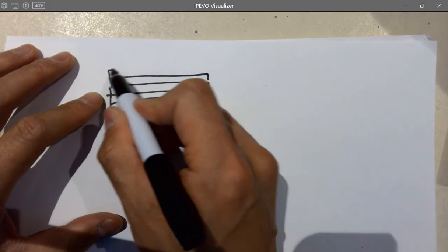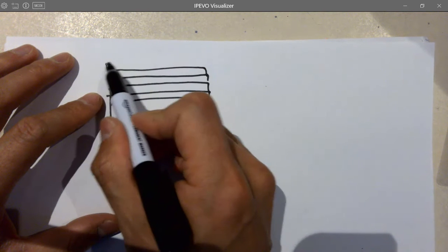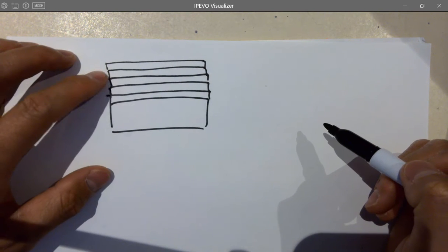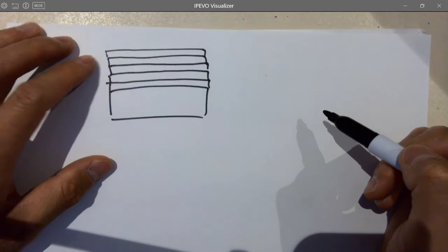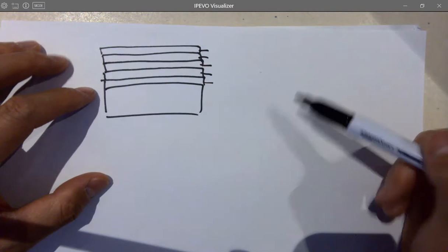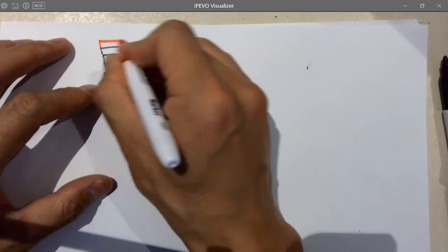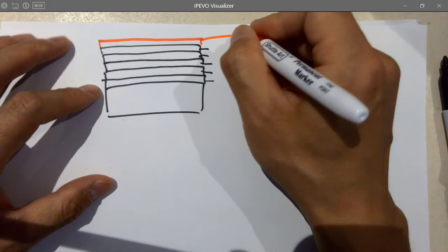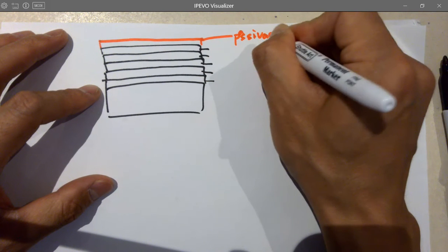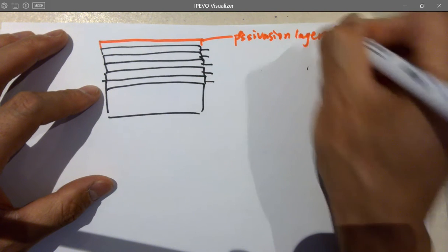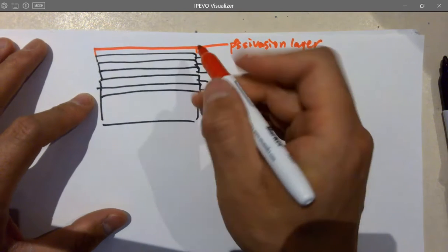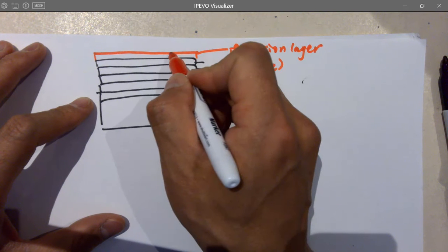Let me know when I should stop, okay? Do I need more? Huh? Really? Let's see. Fox, poly, metal 1, metal 2, metal 3. So the top layer is another, it's called the passivation layer. It's also a silicon dioxide, but it is able to open up a window.